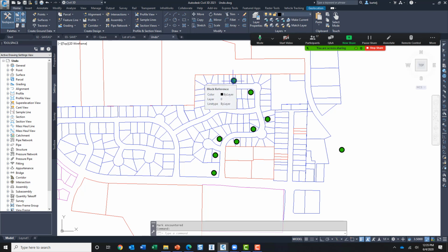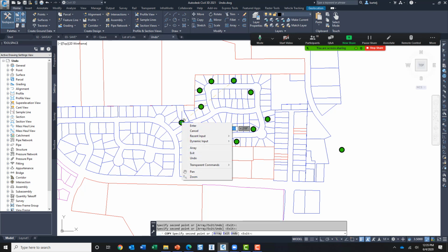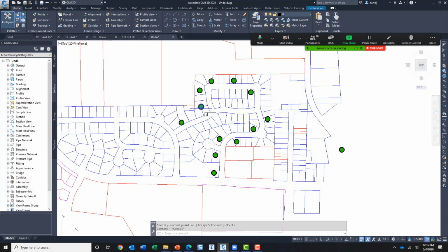Now, the cool part about that is we can actually stack markers. So if I were to, we'll go ahead and say undo. We'll put a marker down here again. We'll say copy. We'll start to create some additional objects here. We'll reach a point in time. I'm going to type in undo again. We'll drop another marker. And I can keep dropping these markers at different points in time as I work, and then I can restore back to those points if need be.